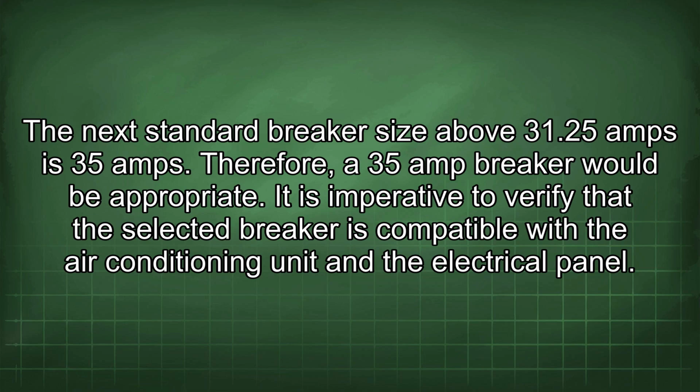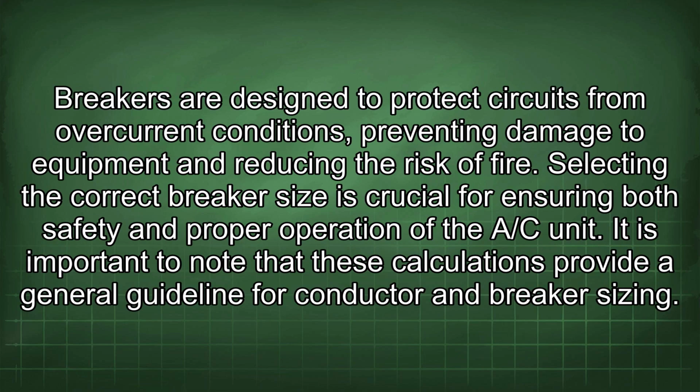It is imperative to verify that the selected breaker is compatible with the air conditioning unit and the electrical panel. Breakers are designed to protect circuits from overcurrent conditions, preventing damage to equipment and reducing the risk of fire. Selecting the correct breaker size is crucial for ensuring both safety and proper operation of the A/C unit.